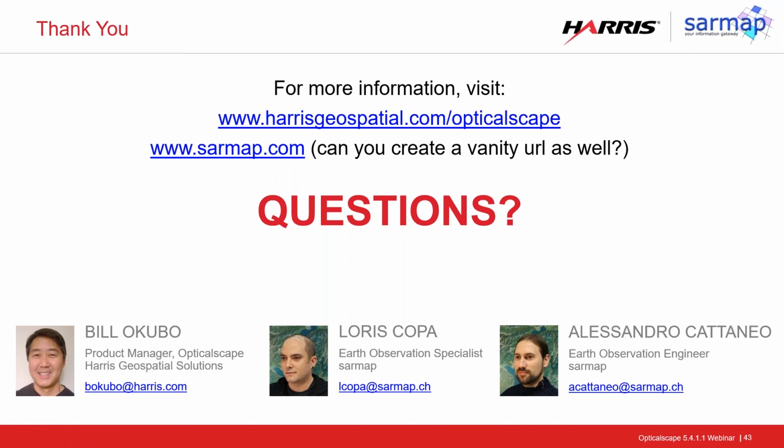The first one, are GCPs mandatory? Well, GCPs are not actually mandatory, but a minimum of 3 tie points has to be provided to the DSM Generation module for Spaceborne. While for UAV, this is not mandatory since we have provided a tool that automatically extracts tie points. Of course, if you don't use ground control points, there is a high probability to have a geographic displacement of the results. Next question. Do I have to select tie points manually? Well, it was partially answered with the previous answer. For Spaceborne, you have to select them manually at the present time, while for UAV, there is an automated module for this.